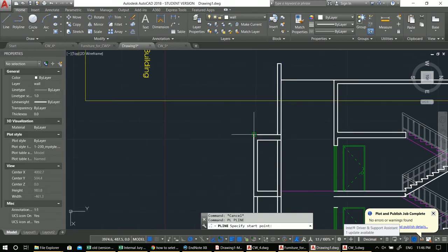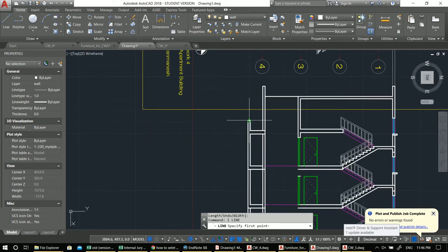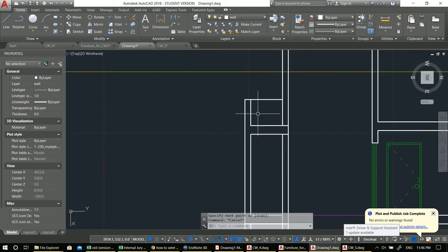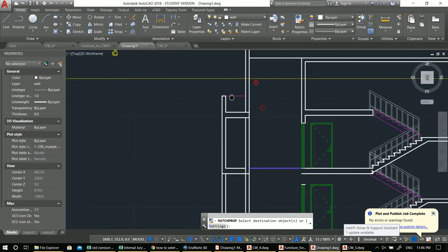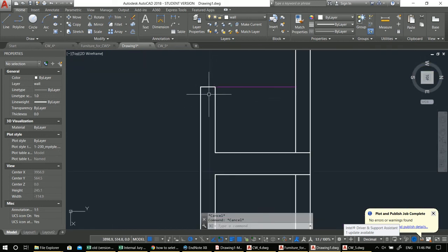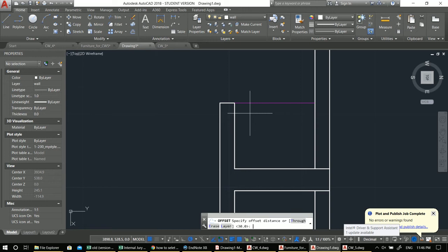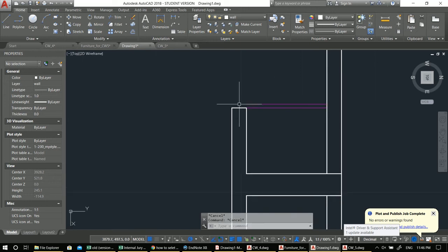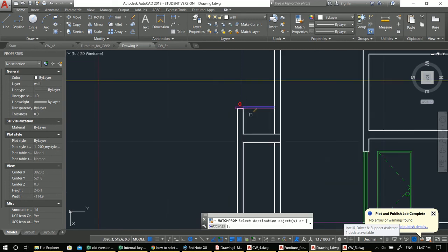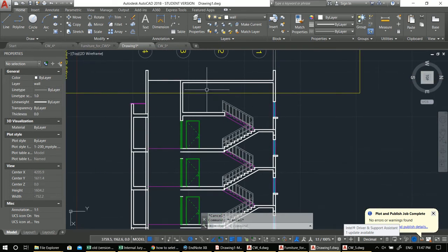We'll have a parapet wall here, let's say 90, 20, and then you will have the elevation line. Usually you have a detail here as well. For the parapet wall, you will have a stone here or something to cover it up. Usually we show it in 1/100, even if it's barely visible because it's around 5 centimeters. I'm just eyeballing it because I don't want to waste your time. So you'll have something here.